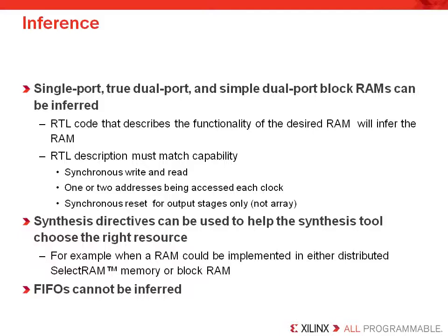So if you're using XST, check out the XST user guide for both attributes as well as coding examples, or refer to your synthesis vendor's documentation to learn how to infer the block RAM memory or FIFO with that synthesis tool. Now keep in mind that there are specific directives for the type of memory you want to infer, such as when you are building either a distributed select RAM or a block RAM. Likewise, the coding style will vary by the resource you're targeting. Also note that FIFO resources have limitations on their inference, but in the end, it's generally easier to just instantiate the component after customizing with the core generator and then add it to your design directly through instantiation.